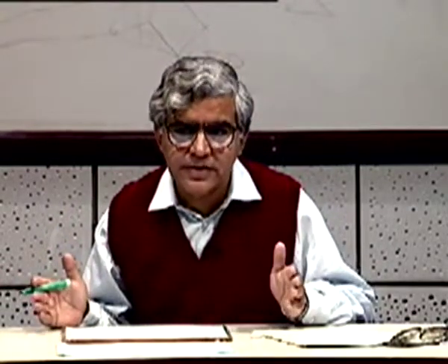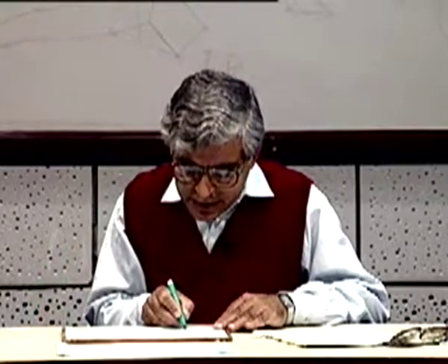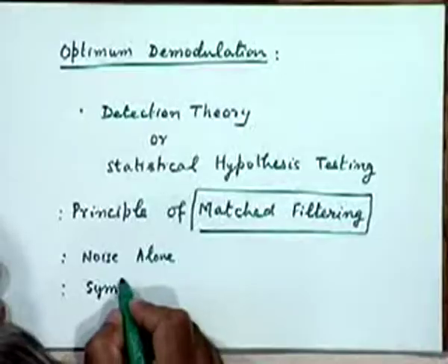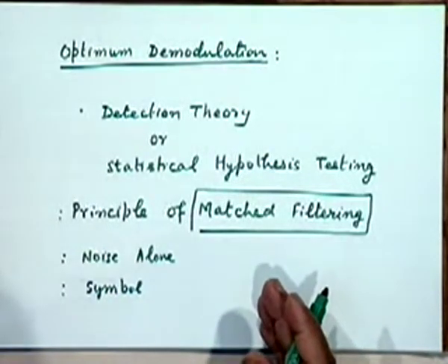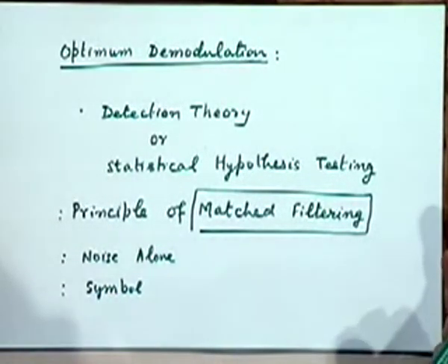No intersymbol interference and no cross interference from other channels. All we have to therefore do is study demodulation of one symbol at a time, provided we know the starting point of a symbol and the ending point of a symbol. The waveform corresponding to one symbol interval.